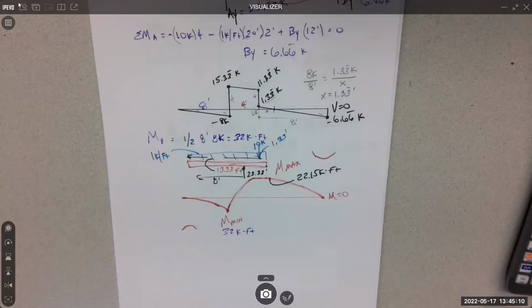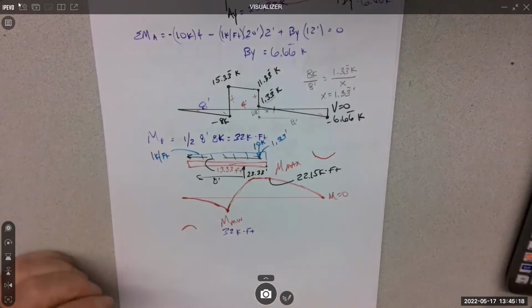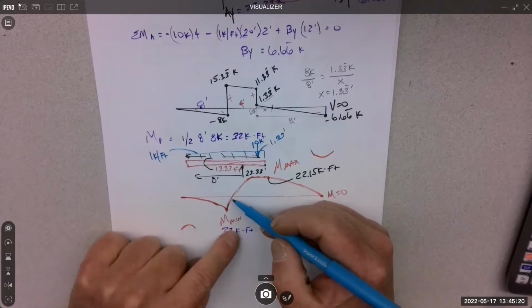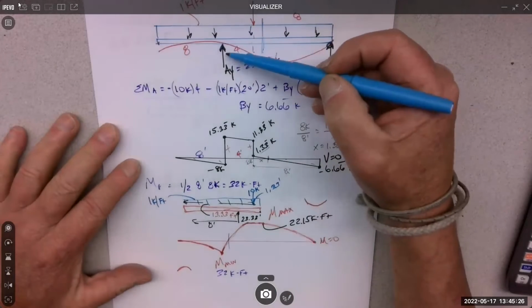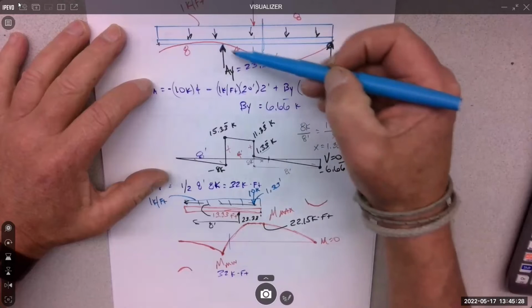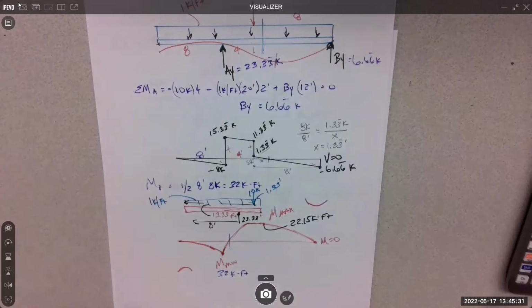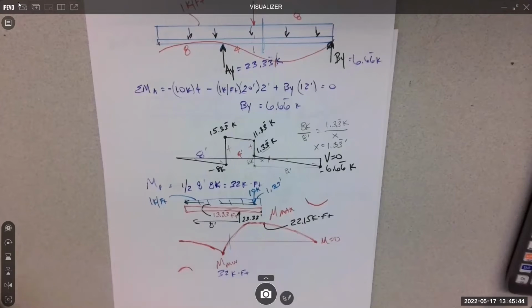Nothing, because there's no next diagram. Just shear moment diagrams, all we have. So when it crosses, that just means that's the point, like that's the inflection point. Would that be, yeah, that would be the inflection point. Up here that would be from this way to this way, right? Where the concavity changes. Yep. Good, super good. Which is fairly important for deflection, but we'll get there when we do that.